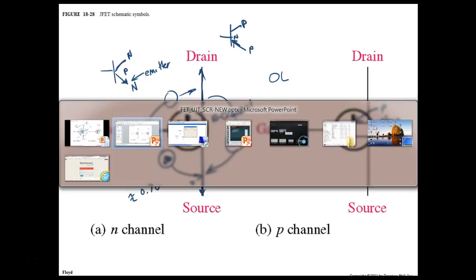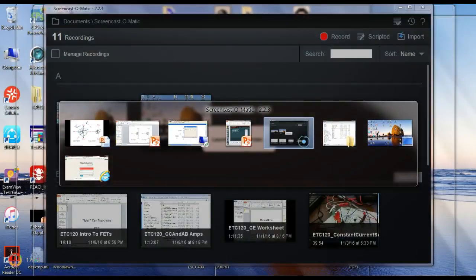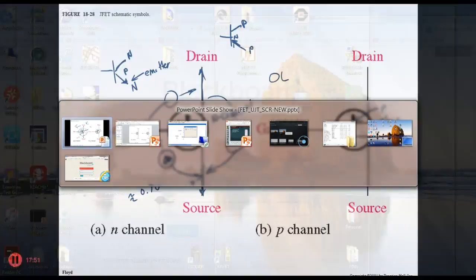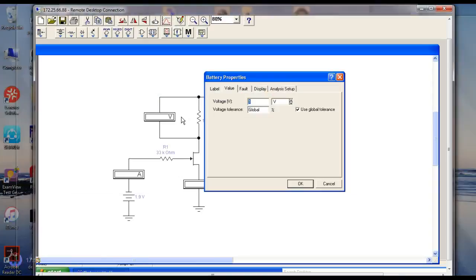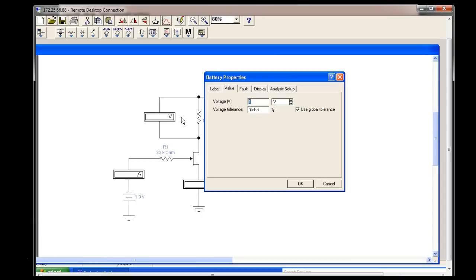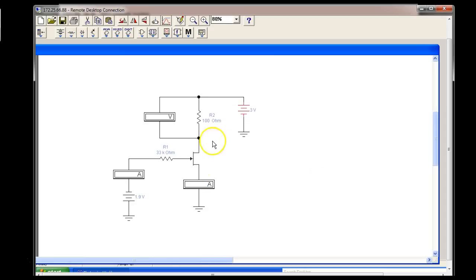So what we're doing here on our electronic workbench is looking at an N-channel FET. Now, if we're looking at source current, I could have put the ammeter up here in the drain. It would have been exactly the same thing, to measure the drain current or the source current, but usually we say the drain current.